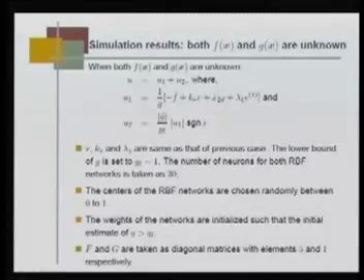Okay. In the first part we put the radial basis function network only for f x, with g x known. Now, we have to put both f x and g x in radial basis function networks, and our controller u is u 1 plus u 2, where u 1 is this one, and u 2 is given; this is the sliding mode term. Okay. R, k v and lambda 1 are the same as in the previous case.